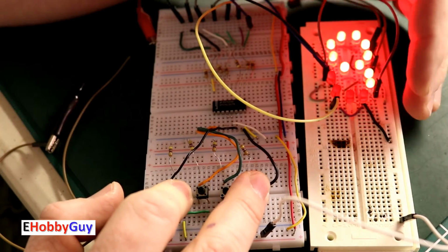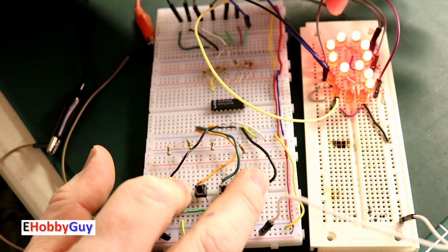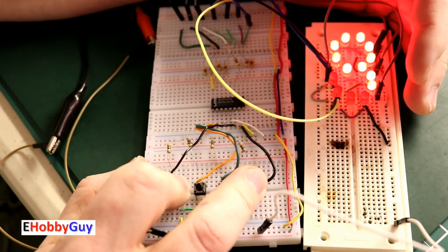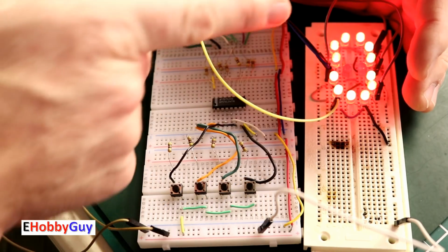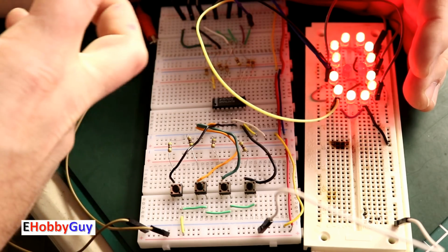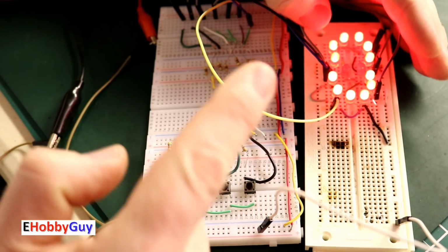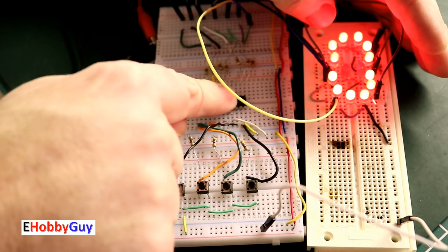Looking at my display here, there's enough sinking current in each one of these to drive 2 LEDs. But what if you wanted to make a 7-segment display in a billboard or something very large like a time clock, a sports time clock, you could easily trigger a transistor that can handle many LEDs. So just keep that in mind, that right off the chip we can drive 2 LEDs from each one of the outputs.